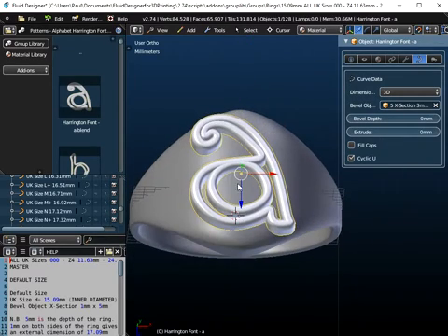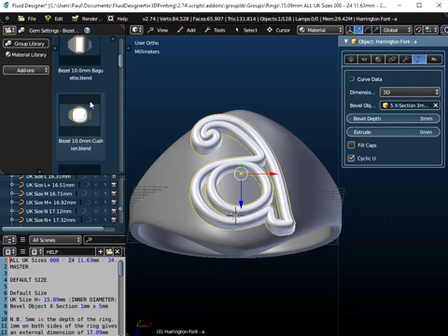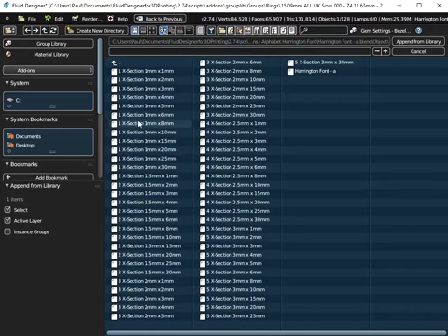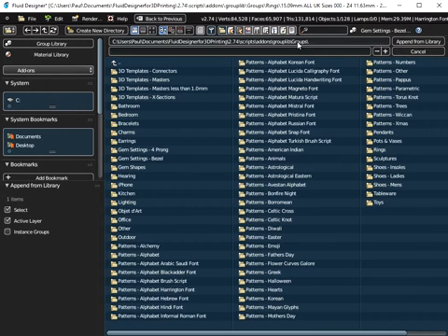So now what I want to do is put a gem in the top here, and as I showed you previously, I'm going to use this bezel type gem. I'm going to use a round gem. So I need to append those to my workspace. So if I go to File and Append, and just go through the menu system until you get Groups again, and that object that I've just shown you there was a bezel.